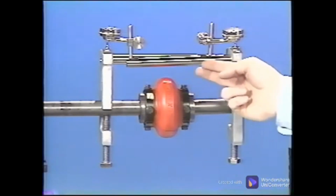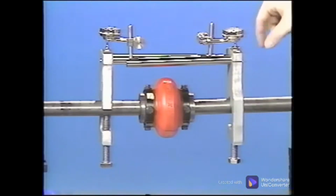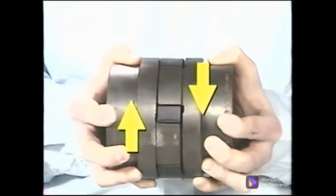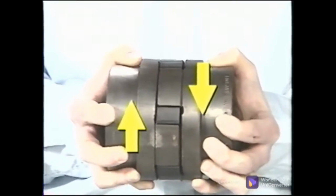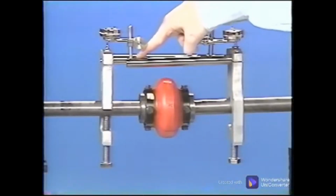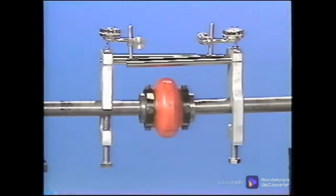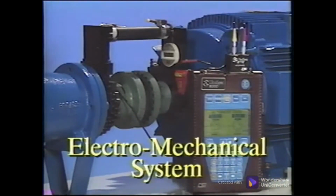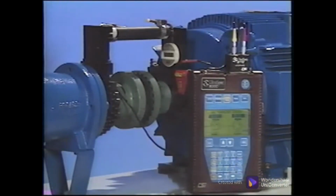Axial movement does not affect the measurements, because the dial indicators do not measure in the axial direction. However, if the coupling has any torsional shift as the shaft is rotated, then error will be induced into the reading, and the bar holding the dial will have some amount of sag that needs to be compensated for. The reverse dial indicator method can be simplified with electronics, such as this CSI Model 8110, which uses a patented method to automatically compensate for bar or bracket sag.